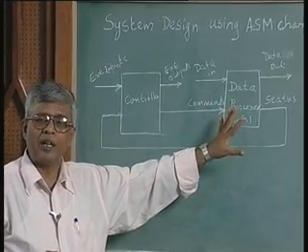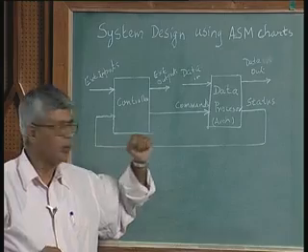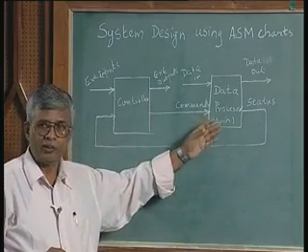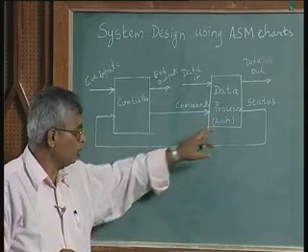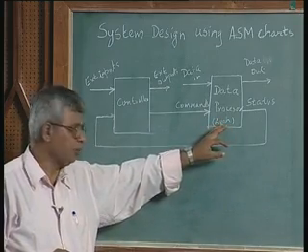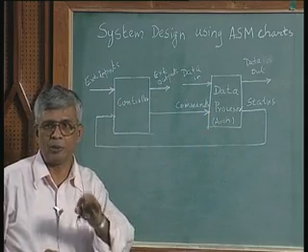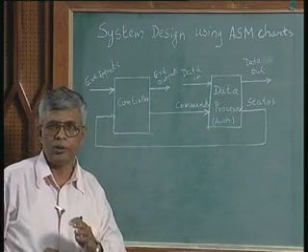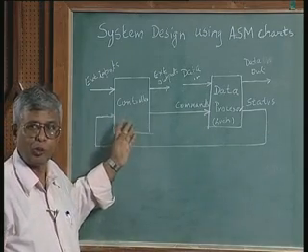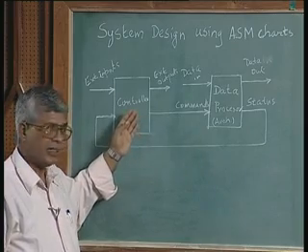are usually elements which are available, functional blocks which are available. A multiplier can be bought, registers are available off the shelf, an adder can be purchased. So, most of the time the architecture's functional blocks are available off the shelf. Sometimes you may not have the exact specification, but you may have to work with that. On the other hand, the controller is what you design, this is specific to the problem you are designing, specific to the design. It is designed by the designer.